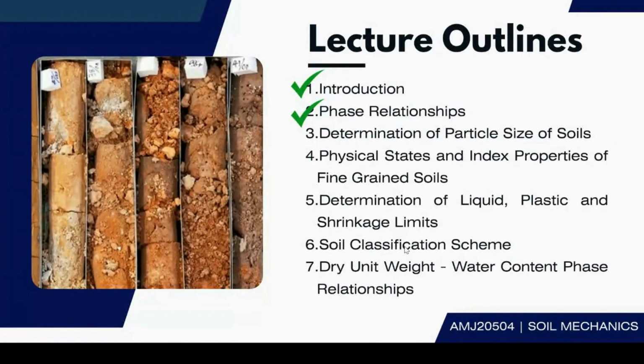How do you differentiate the type of soil for hydrometer and the type of soil for sieve analysis? Hydrometer is for fine grain soil. Sieve analysis is for coarse soil. Good. Coarse grain soil and also fine grain soil. We have gravel, sand, silt and clay. Gravel and also sand, we categorize as coarse grain soil. Remember this.